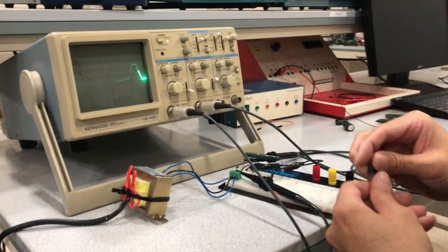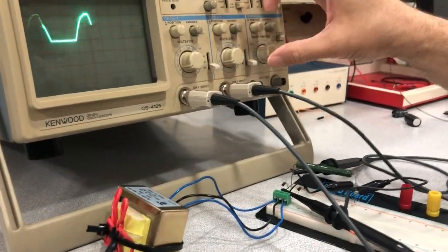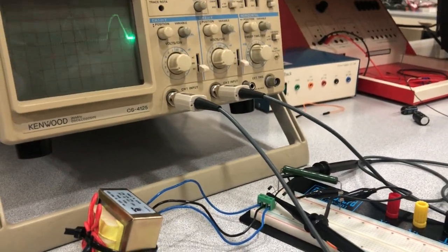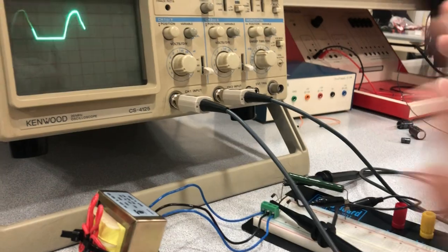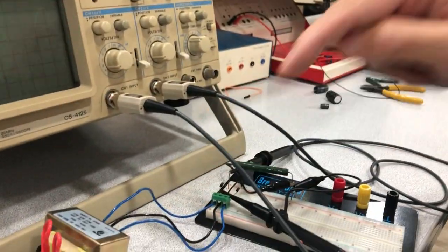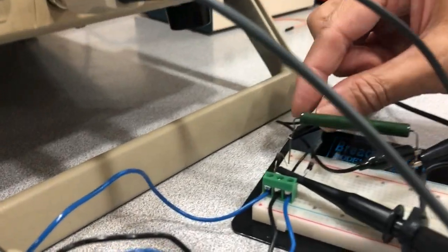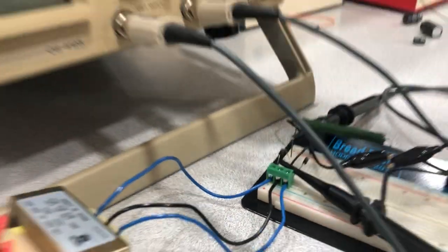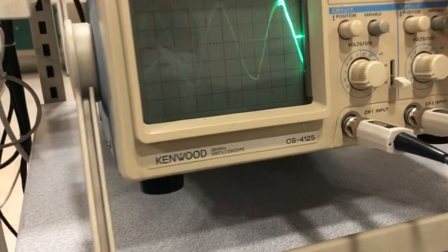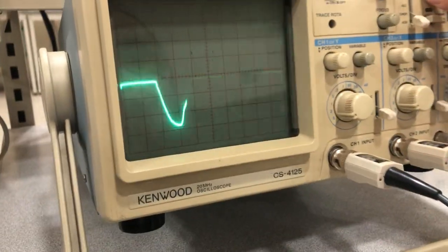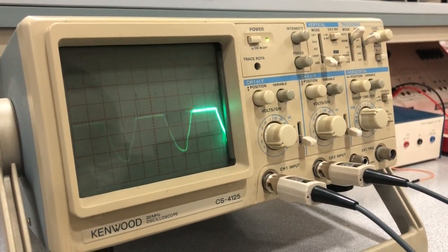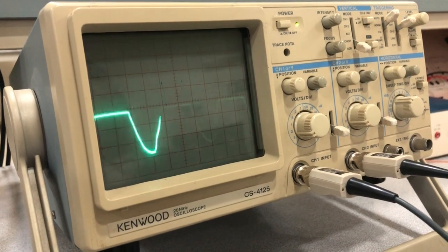So now, to see them both, I want to measure the voltage diode drop using subtraction between two signals. I've put probe 1 on the left and probe 2 on the right. Let's plot them together. I can go to add, I can go invert 2. So it's subtracting 2 from 1.